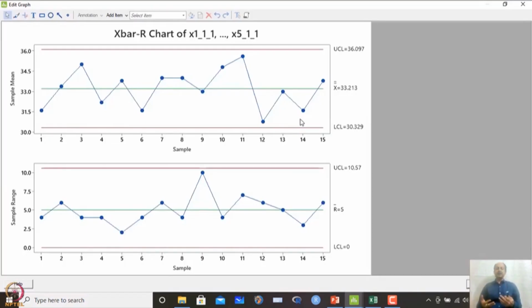We have eliminated 5 points, and after we have eliminated 5 points, we see that all the points are within control limit. So, this UCL and LCL that we get have natural variability only within this. So, there are no abnormal scenarios, and this chart with no data plotted over here, the central line, upper limit line and lower limit line, will be delivered to the personnel who will monitor the process with respect to time in future, like that.